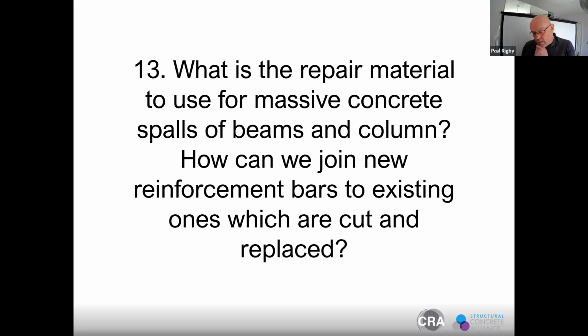With regard to reinforcement, joining it together, generally within the industry, we look if 10% of the mass of the steels have been eroded away, corroded away, then we look to replace or supplement that steel. And that can be welded on, it can be spliced on, but you've got to consider the actual lap of what you're doing from a weld to the lap, and when you tie it on, it should be 15 times the diameter of the bar, or around about 300 millimeters, depending which is the greater equation.